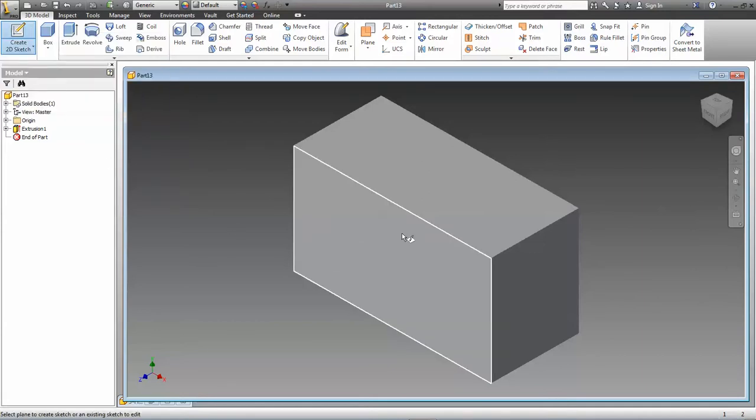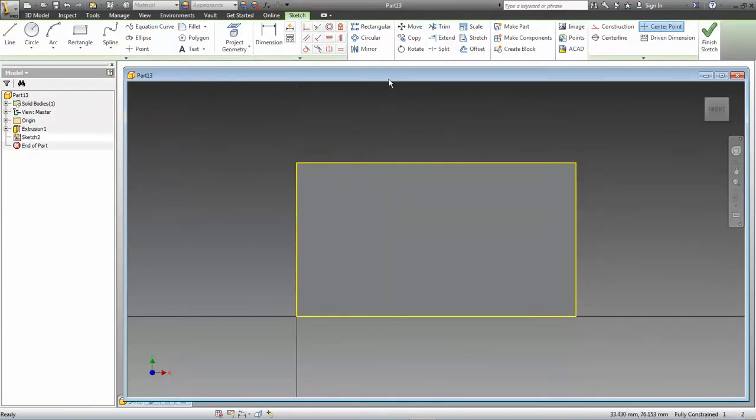So the first thing I'm going to do is create a sketch in the front. And I'm going to create a work point up here on the ribbon, which is going to be right in the center, left and right, which is x coordinate 45, y coordinate 10 millimeters. So if I tab over, I can type in 45, 10, click there, there's my work point. Now the rest of the triangle I can create just using the line command. And I know we need to start 10 millimeters from this side, so the x coordinate is 10, the y coordinate is 50.